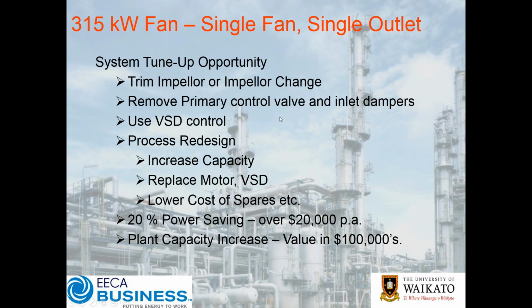Alternately, if everything is just being grossly oversized, we can do one of two things. We can actually change the impeller. We could trim it or fit an actual smaller impeller. We could reduce the width of the impeller as well as just the diameter. We could then look at removing the primary control valve and the inlet dampers. Then even still, we may still need VSD control.